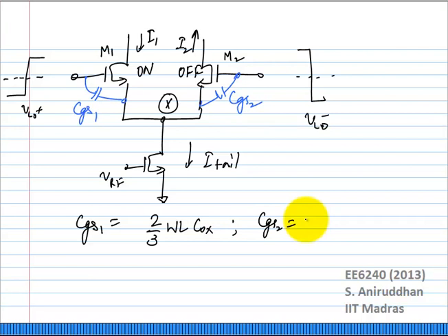No. It will only be the overlap capacitance. The other capacitance with respect to bulk. Okay. The capacitance with respect to bulk is a fixed capacitance. Whereas here we are interested in the gate source capacitance specifically, as you will soon see, because the gate node is experiencing a transition. That is why we are interested in this capacitance. I'll call it LD, which is the overlap capacitance.